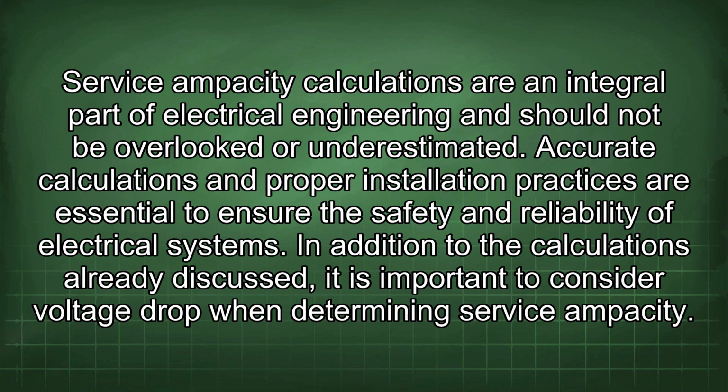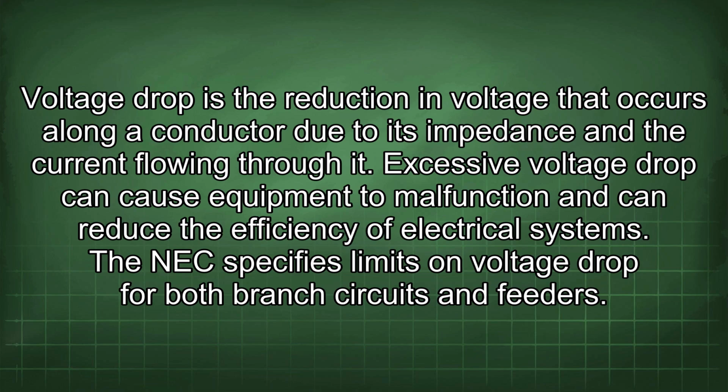In addition to the calculations already discussed, it is important to consider voltage drop when determining service ampacity. Voltage drop is the reduction in voltage that occurs along a conductor due to its impedance and the current flowing through it. Excessive voltage drop can cause equipment to malfunction and can reduce the efficiency of electrical systems. The NEC specifies limits on voltage drop for both branch circuits and feeders.